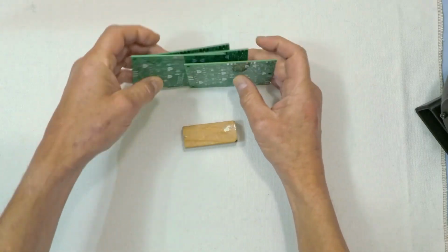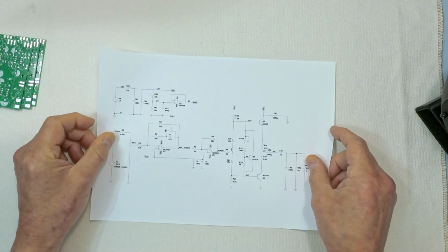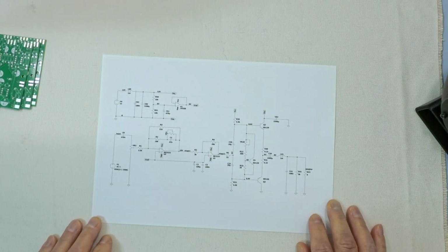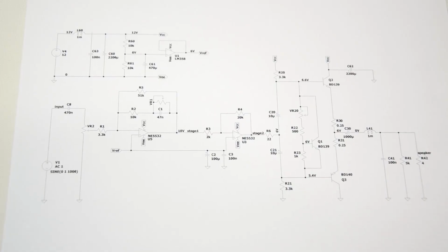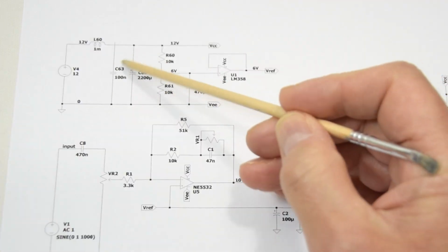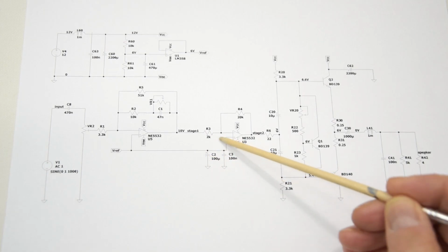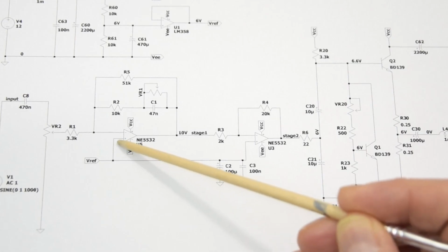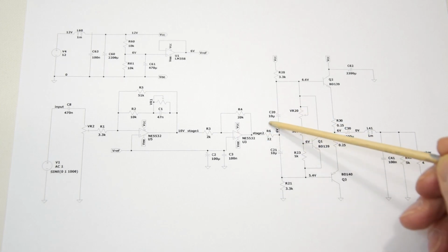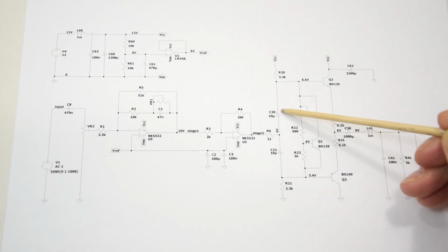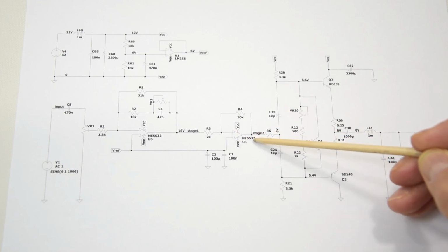Okay, so I've updated the schematic one last time. So if you're thinking of building an audio amplifier yourself, this could be a solid starting point for your project. Let me show you the optional components I put in. So I added an extra optional cap here, 100 nanofarad. I've added some extra caps here, optional, to buffer the reference voltage near the op-amps. And I've added an optional resistor here that can be placed if the capacitive load is too large to be handled by the output of the op-amp.